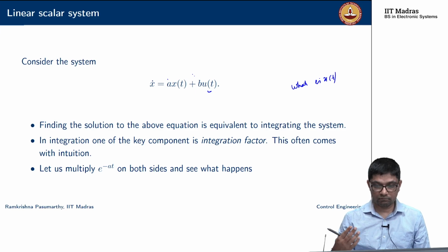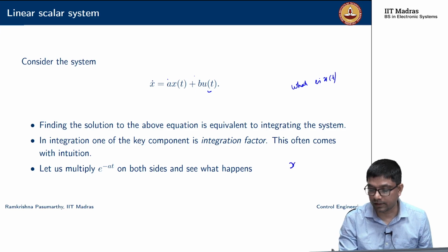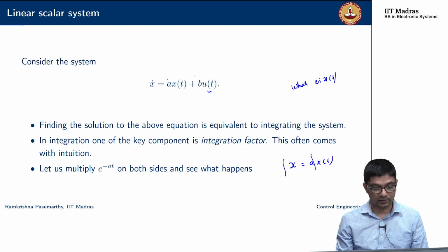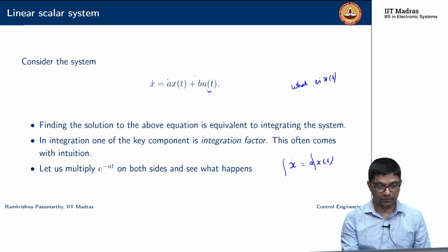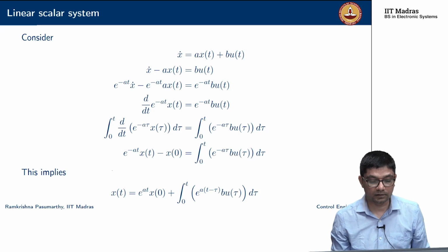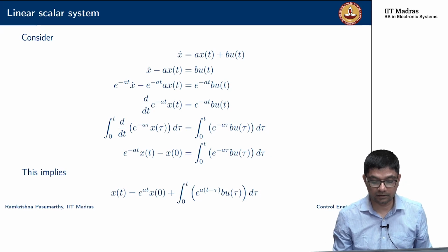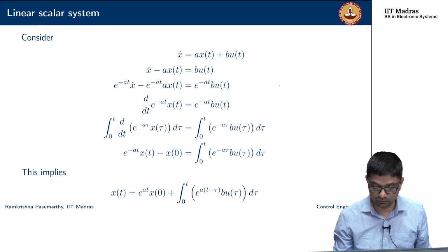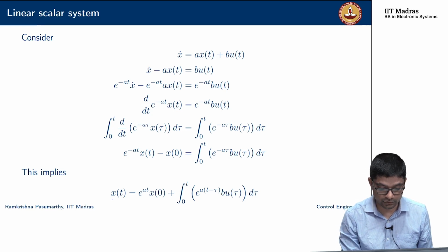Okay, so the solution of x dot equal to Ax came via integrating both the sides and using standard tricks that we learn in calculus. We'll still do the same, right? So we just multiply both sides by e power at. We write down a series of steps here. I'll not read through those, but what we will end up with is a system with solution x of t is e power at x naught.